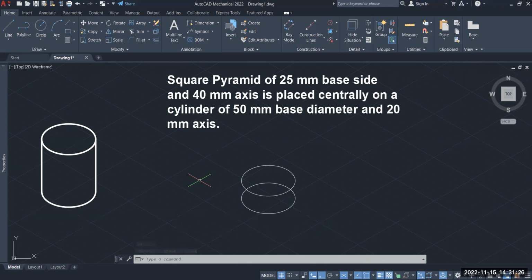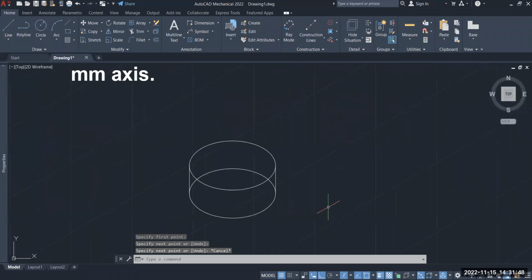Let me change the plane first. L, enter. Here, you will be shown a quadrant point. Click that and go down to the other circle. Again, wherever it shows quadrant, you just click. That's all. Repeat the other side also. So it will become tangent in this case. Okay. Right.